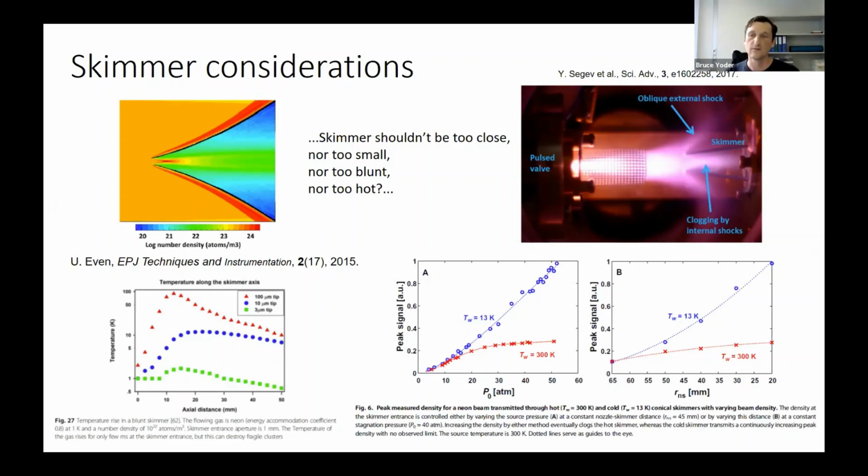The simulation represents the flow of a collimated cold stream of neon atoms and is a good example of a clogged skimmer. The base of the skimmer has less than 2% of the incoming beam intensity. In this case, the skimmer shape is wrong and the entering beam intensity is too high.